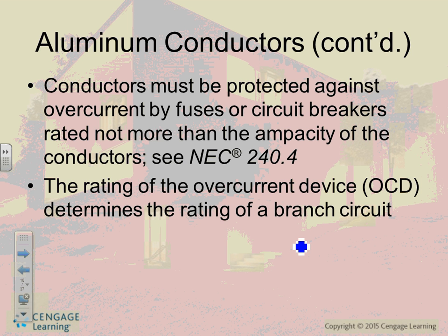It conducts better, so it gives you more amps, and it doesn't expand and contract, so it's safer. Copper, two words for copper. Safer in terms of arc flash, arc blast. It doesn't expand as much, and it conducts more, and you have a smaller conductor to carry the load. Aluminum has two advantages. Three, probably. Okay, cheaper, less money. Lighter, less weight. That's an advantage when you're having bigger feeders. The rest is a disadvantage. So cheaper in terms of money and less weight.